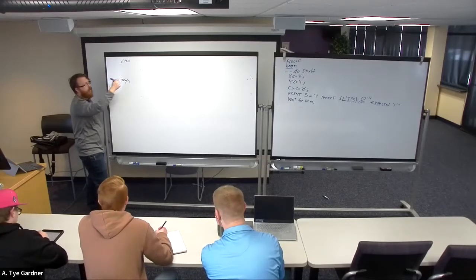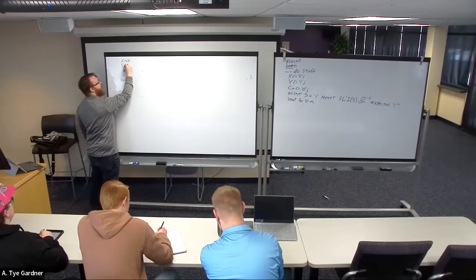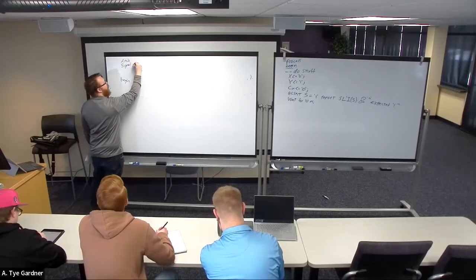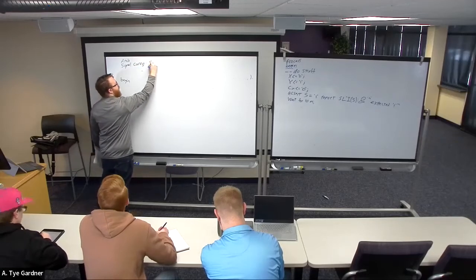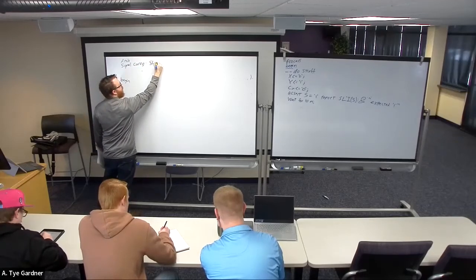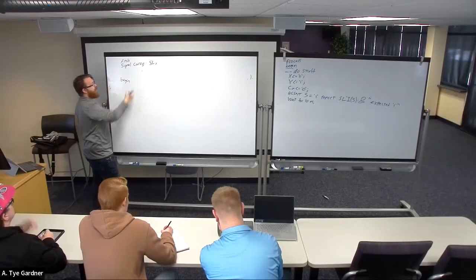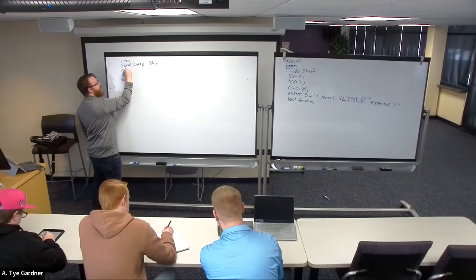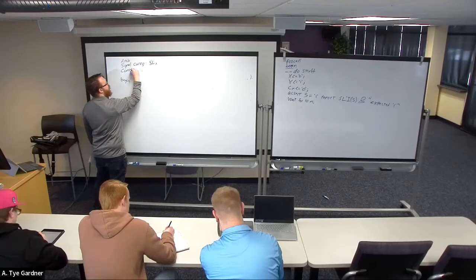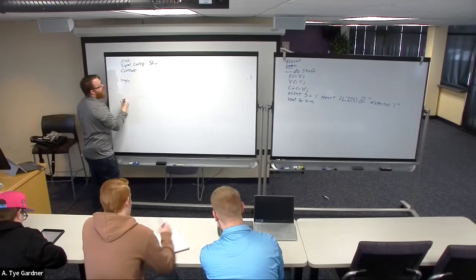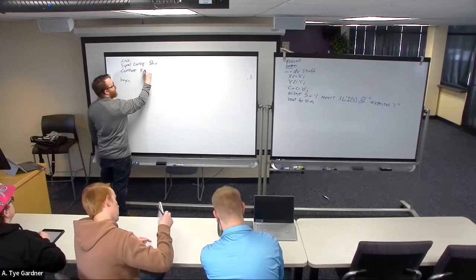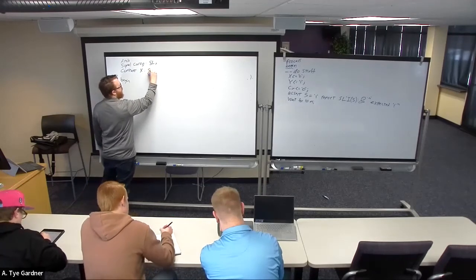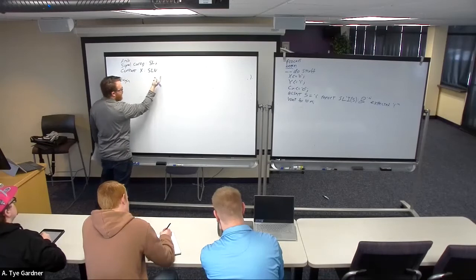Like signals, I could have an internal signal carry that is a standard logic. Now I have a signal that's carry. Well, I can do the same thing with a constant: give it a name, X. It's going to be a standard logic vector, again, shorthand.